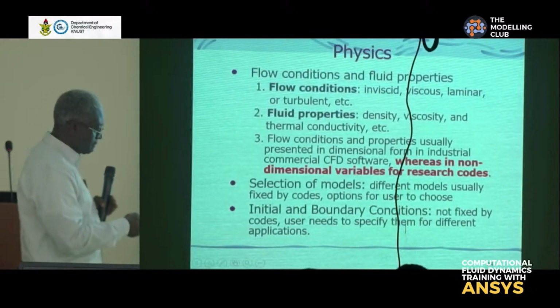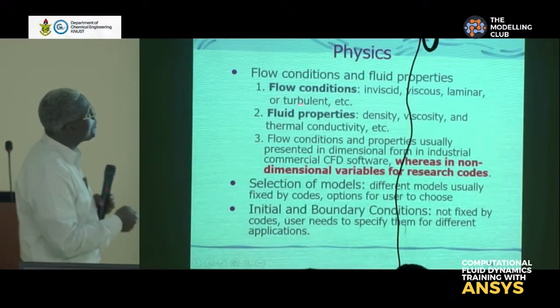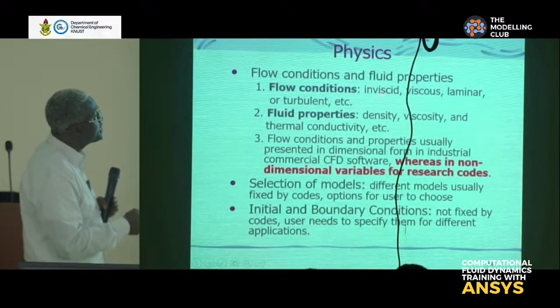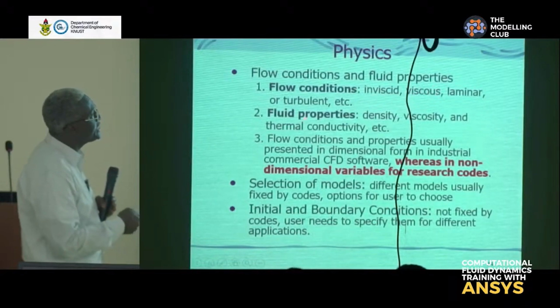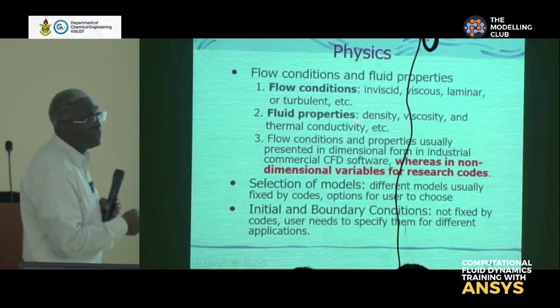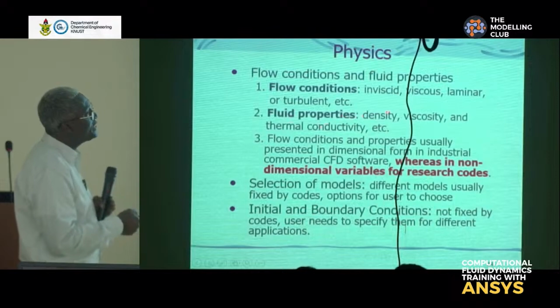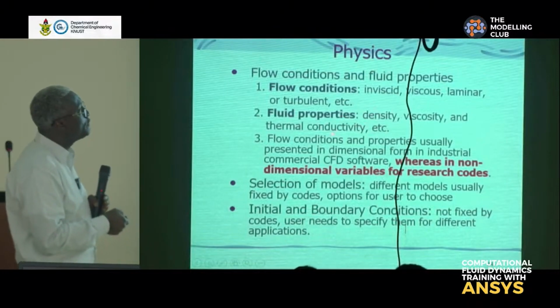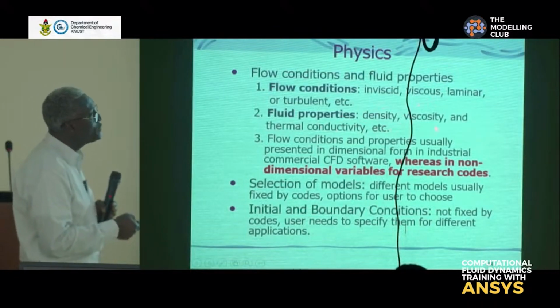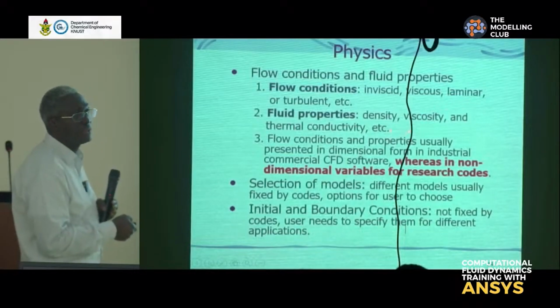For the physics, flow conditions and fluid properties. The flow conditions, is it inviscid, that is no viscosity or viscous? Is it laminar or is it turbulent? Is it isothermal or there's a temperature dependence? Fluid property. What are the fluid properties needed for the solution? Do I need density? Do I need viscosity? Do I have thermal conductivity and so forth?